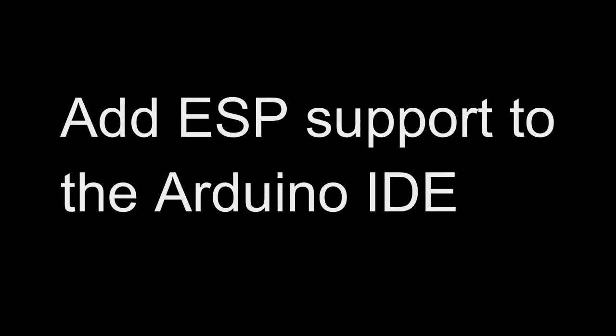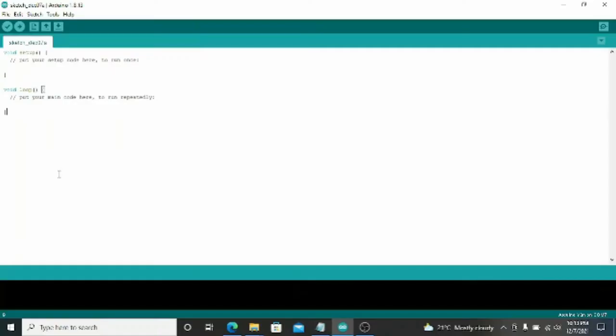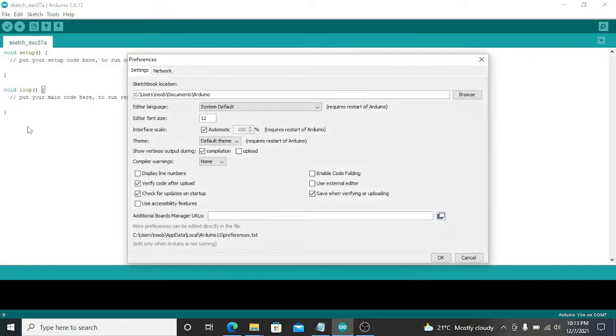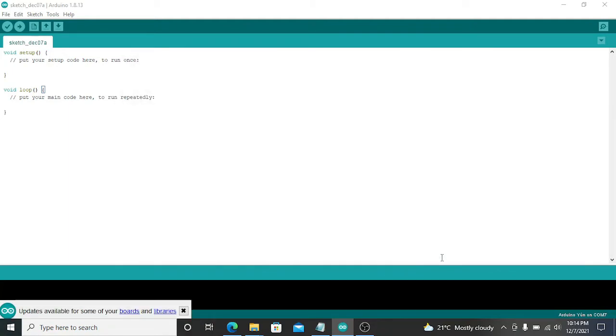First install the Arduino IDE. It only comes with ARM processor support, and we need to load support for ESP. Go to File, Preferences, and open the dialog. Turn on verbose compilation so that we get more lengthy error messages during compile, and paste in the URL that gives us ESP8266 processor support. That's in the project notes.